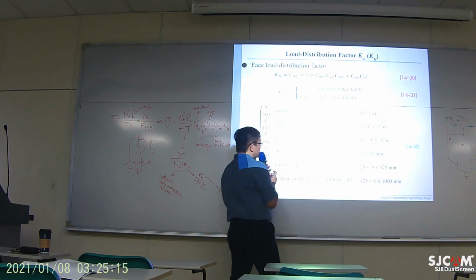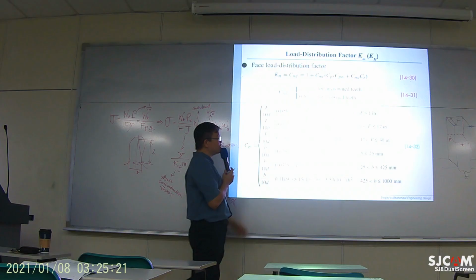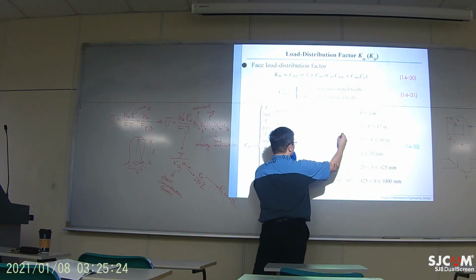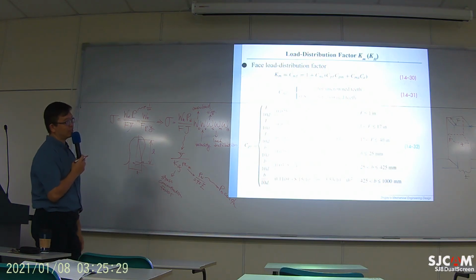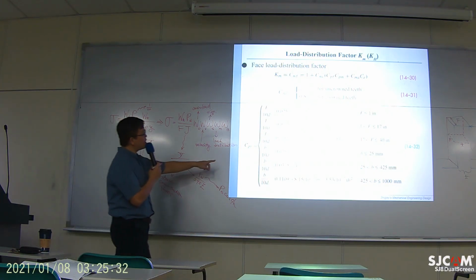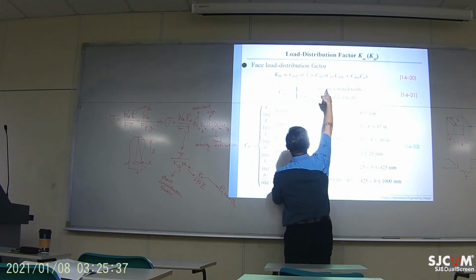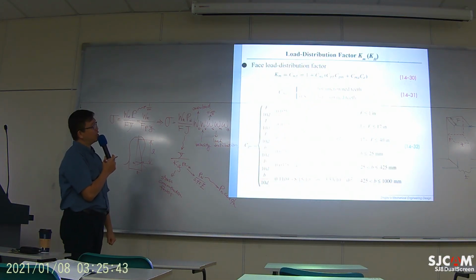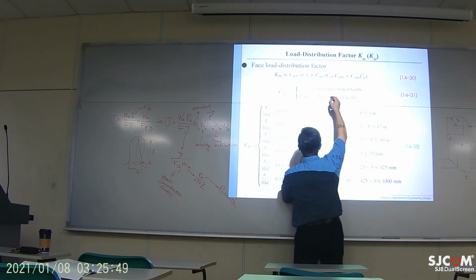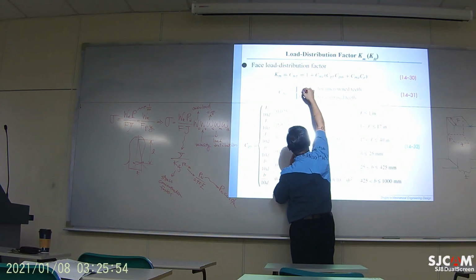Whenever you see very unique coefficients and some functions, again, that is a result of curve fitting. So when you apply this C value and also this C value, plug them into the top equation, then you compute your load distribution factor. And over here there is a pre-multiplier telling you 1 or 0.8.